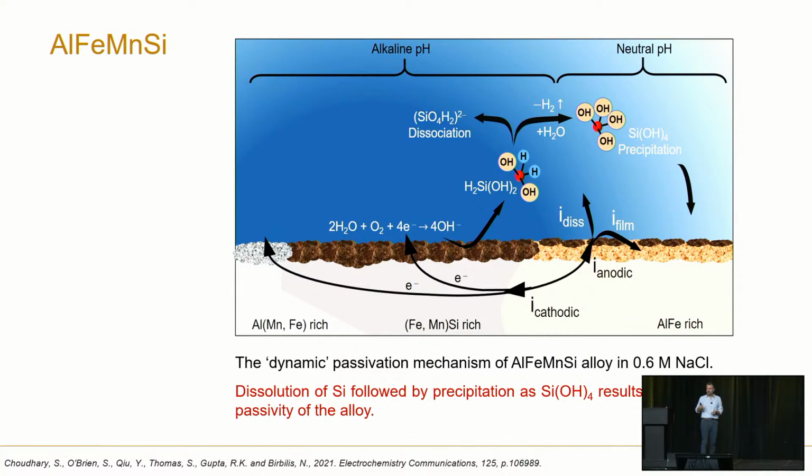Now, everyone's looking at it from a different perspective. I've tried to talk about lightweight high entropy alloys that are corrosion resistant. Other people are looking at refractory high entropy alloys or coatings that are high entropy alloys. So there are different situations for everyone. You probably wouldn't want to use this alloy at extremely high temperatures, but of course nickel, cobalt, chromium based or refractory type high entropy alloys could be suitable for things like aero engines, to make them go hotter, faster.